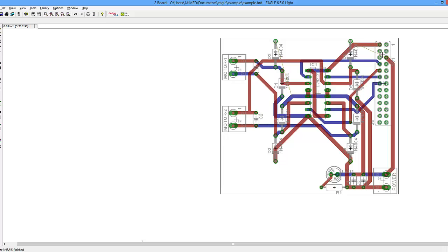So this is where you guys come in. You have to do it yourself to fix it. But see, the problem with the auto router is this. It thinks that you have access to a board shop machine that can do whatever PCB you want, whether double layer, triple layer, or whatever. It doesn't know that you are a poor university student or a hobbyist. You are just trying to make a simple PCB out of through-hole components. It thinks that you can solder on any layer, which is wrong.